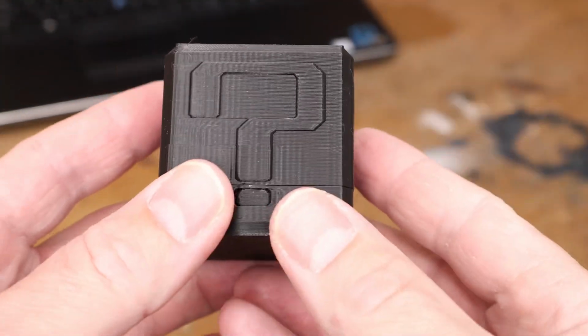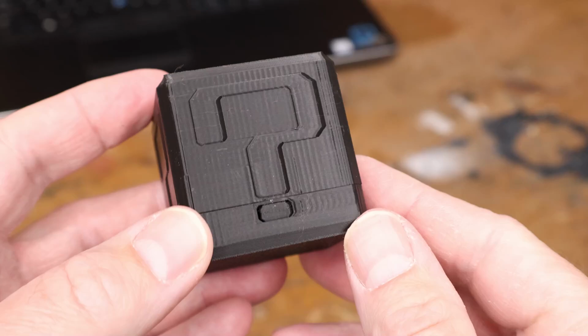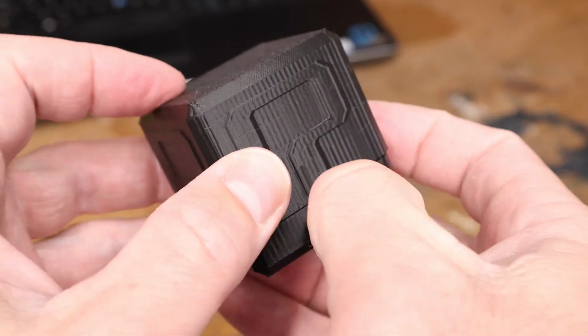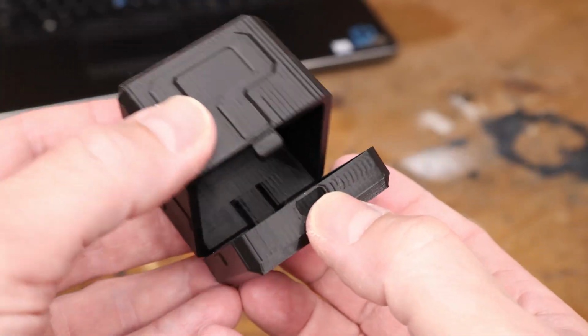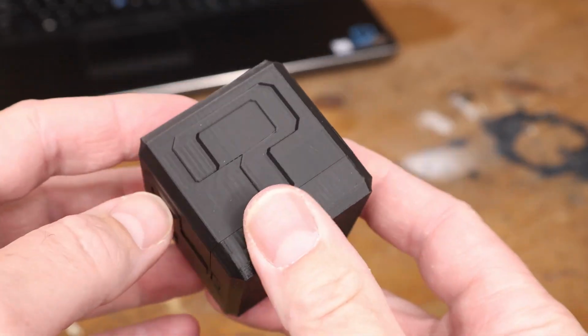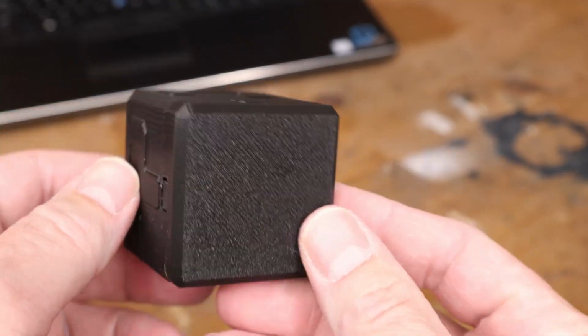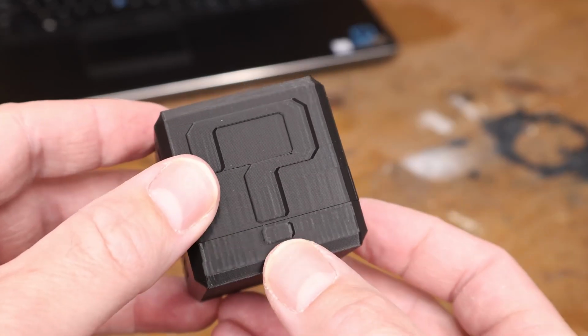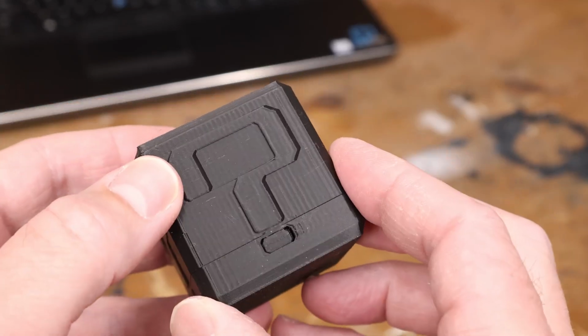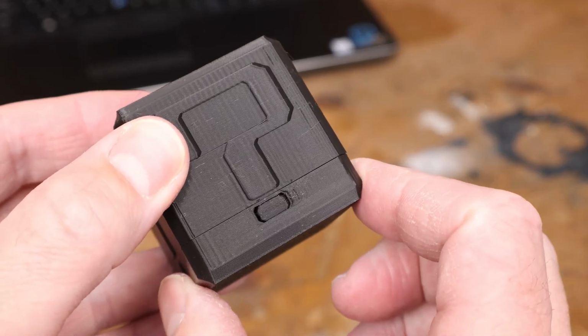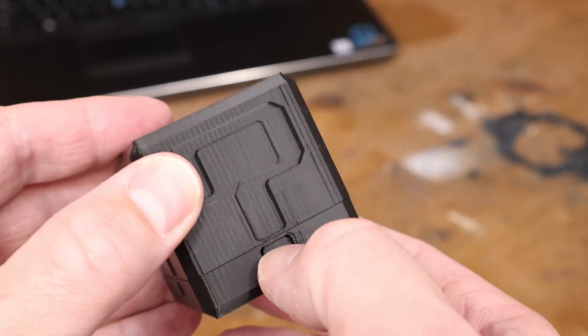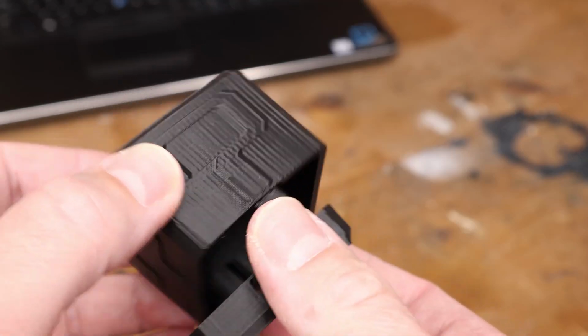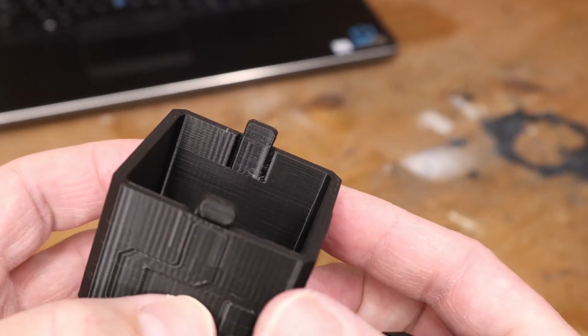All right, so now that this thing is printed, how did it work out? Well, as we can see on the surface, we do have some irregularities, and this is a 3D print setting problem. It doesn't have anything to do with the model itself. But I would say that the gap on the left and right of the little push button that we made could be a little bit tighter. We added, I think it was 0.1 to both sides, a total of 0.2. I think we could have halved that and done 0.05 on both sides.